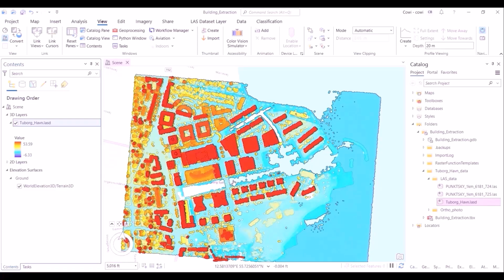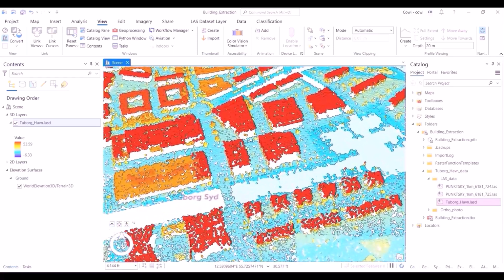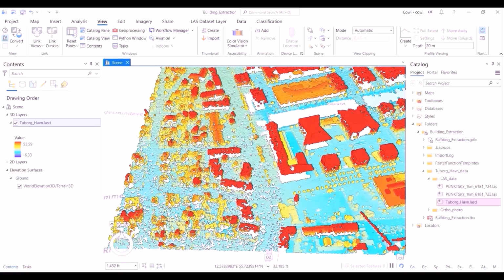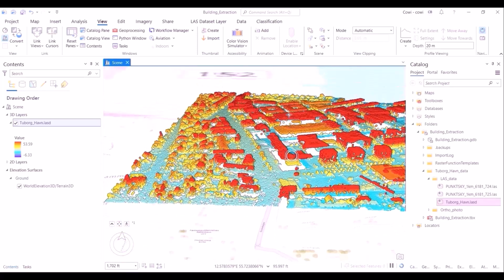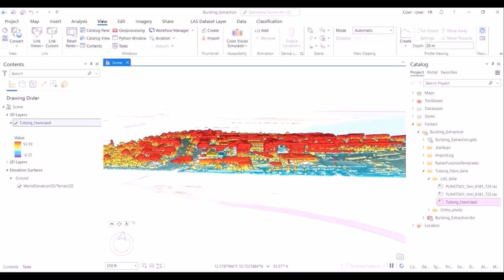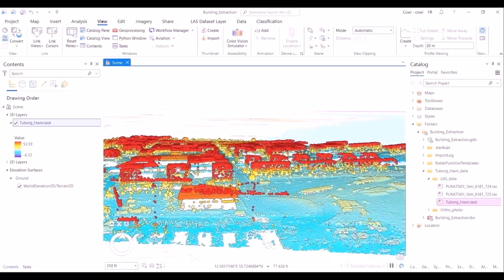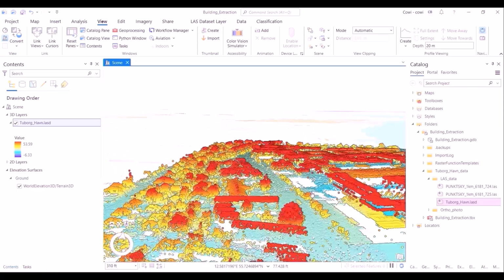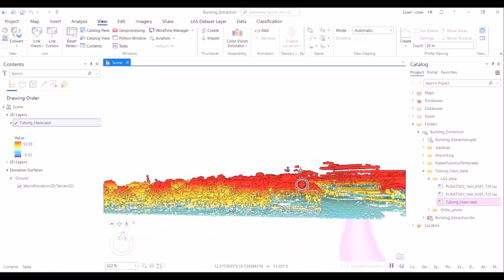So areas with high elevation are typically yellow, orange, and red, whereas the ones with lower elevation values are typically light blue and dark blue in color. Because it is a 3-dimensional imagery, we can zoom in, explore the properties, and see the point cloud for ourselves before we go on to the next processing step.